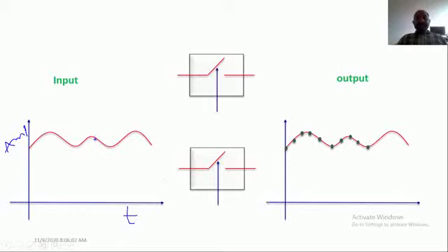And this particular continuous signal should be converted into what? Digital signal, because this information should be processed by the DSP. When you would like to convert the continuous signal, which is the analog signal, into the digital format, you can't convert the analog information directly into the digital format. Actually, you can convert the analog information, which is the continuous signal, into the discrete format first. So that is done with the help of the switch. So the input signal is the analog signal, and the output signal is a discrete signal.